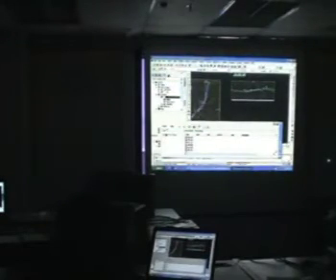So this is very different from Land Desktop and Civil Design. Even though you've never used Civil Design, just to let you know, Civil Design is kind of like Land Desktop. When anything has been done, you need to reprocess everything. You need to reprocess what the sections are, where the position of the new horizontal alignment is. In this case, you just need to move and everything's updated. So you can be very sure in this sense that it is the latest information.